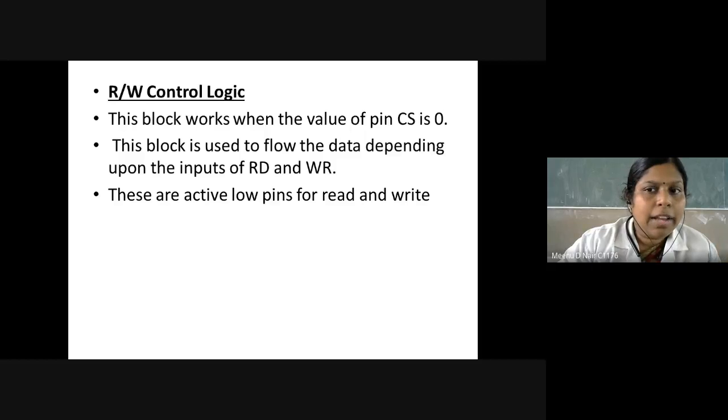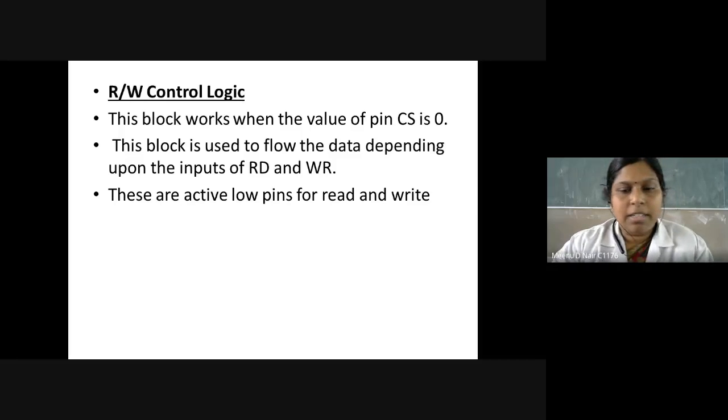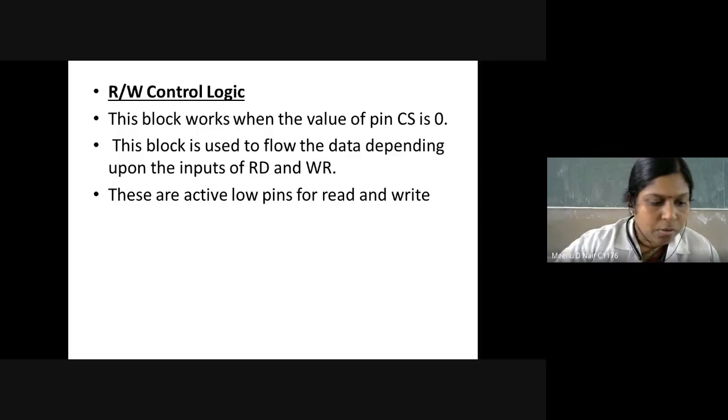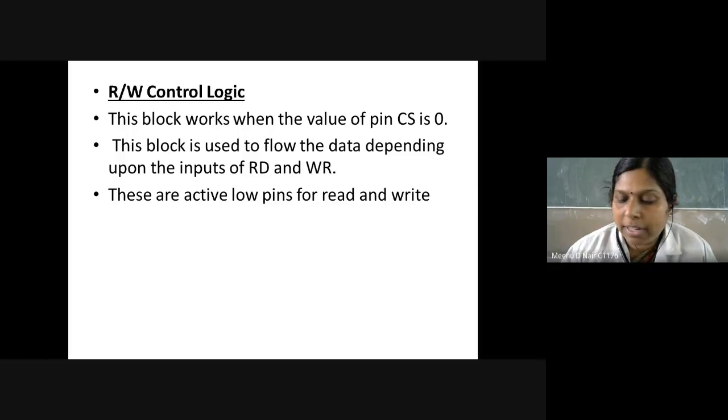Then read or write control logic. Chip select will be at logic 0. Depending upon the inputs RD and WR, that also you know, read and write are active at logic 0. You will know the meaning of the read and write commands.